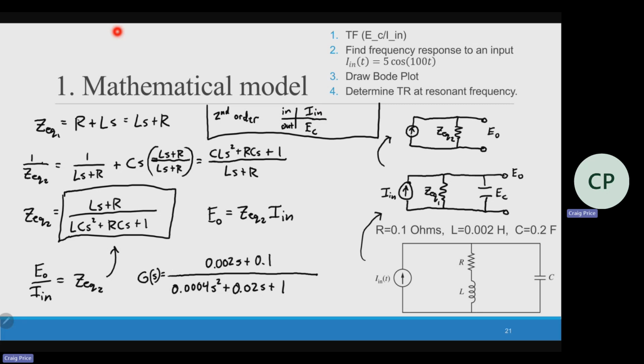All right, so for the next step, you are putting it in standard form, hopefully. Standard form, transfer function. Then, if I want to find the frequency response for a given frequency, that's where we're going to use that sinusoidal transfer function. S becomes omega i. And if I have an i squared, that becomes negative.